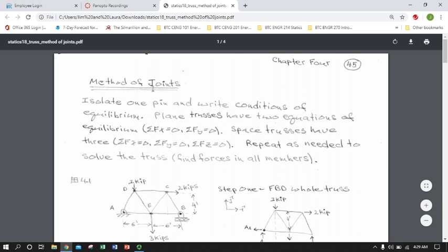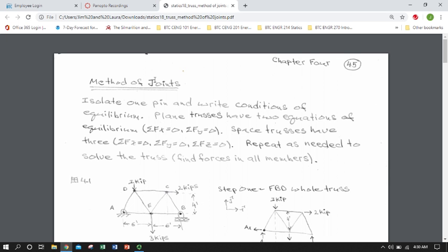This is picking up from our last live lecture on campus, where we went over the definition of a truss: basically a structure composed entirely of two force members, usually something in the real world that's approximated by hinges or a fairly flexible connection relative to the members' bending moment capability, cross-section, or flexural modulus. So we'll have semi-flexible hinges or true hinges